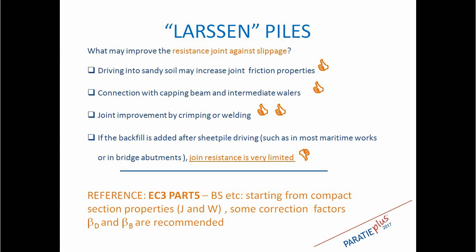But of course, if you drive a sheet pile first and then you add a backfill, like frequently occurs in maritime operations, when you drive the sheet pile there is no soil, but maybe water only, and so in that case the joint resistance cannot be relied on.